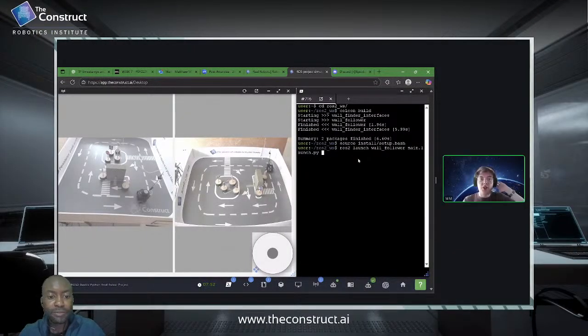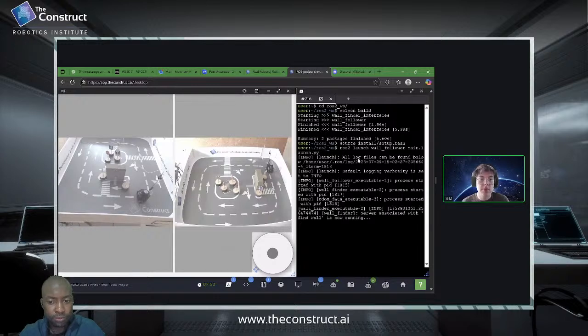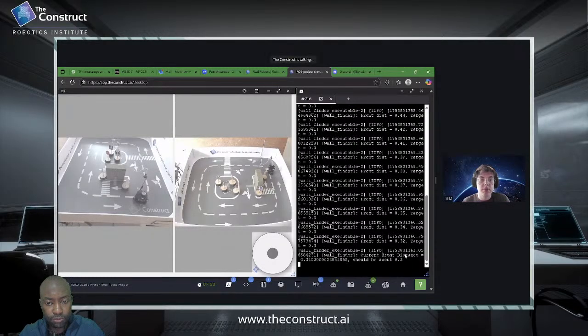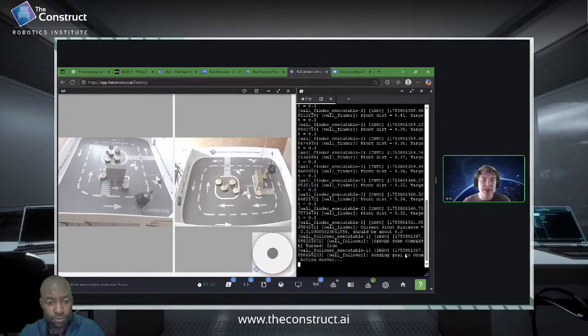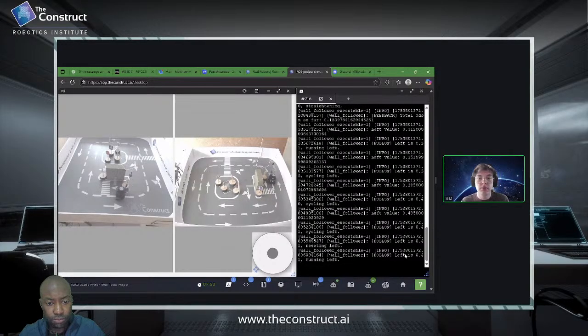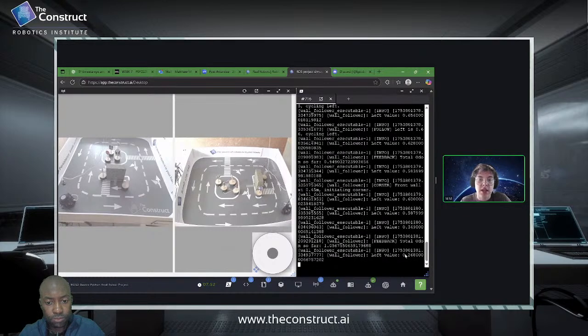Cool. Thank you very much. Let's hope this works. The objective of this program, first it calls a service server to get the robot to move to approximately 0.3 away from the wall. And then from there, it activates an action server to passively keep track of odometry data, like, hey, I've traveled this far, exclusively that sort of thing. And now you'll see it's taking that corner. Just hoping it doesn't clip anything.